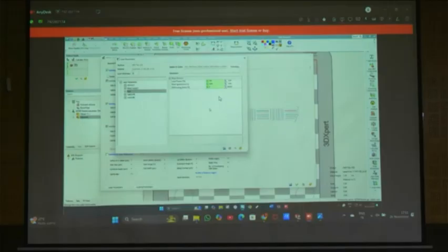Yeah, as I told you, our aim is to focus on the design. One of my co-scholars has printed so many lattice structures using the default parameters only. In my case, I did the process parametric optimization using solid bodies. I calculated residual stresses and solid mechanical properties. Once everything was finalized, I went with the lattices and printed the applications using the lattices. That is how I did it.